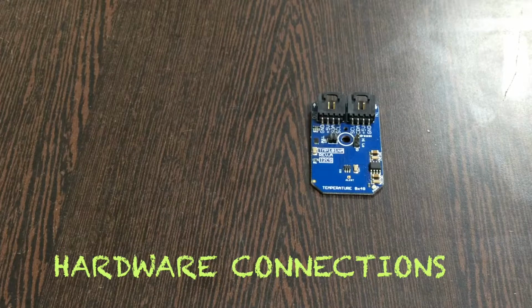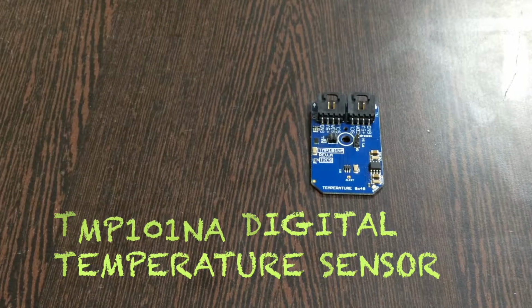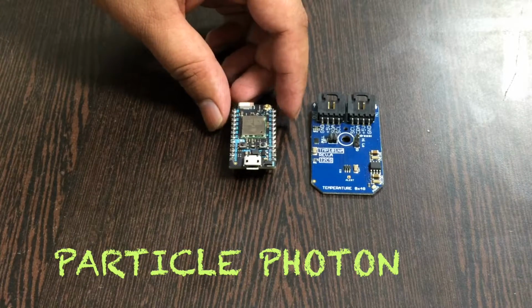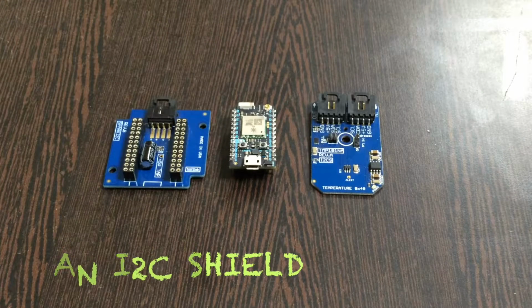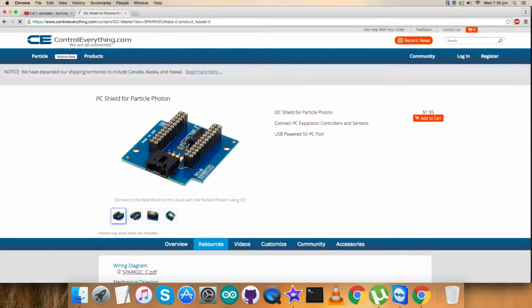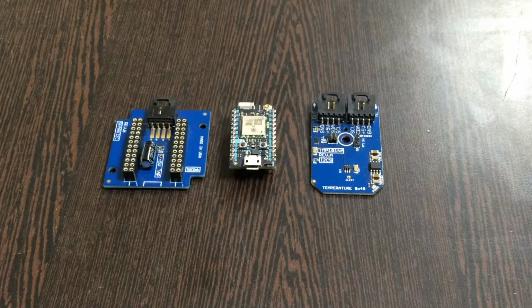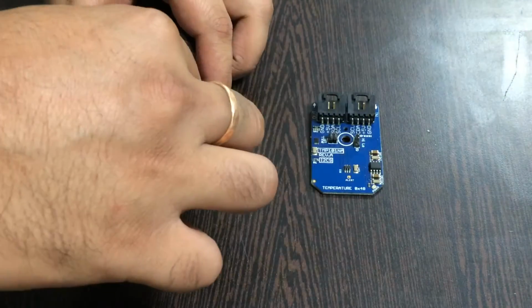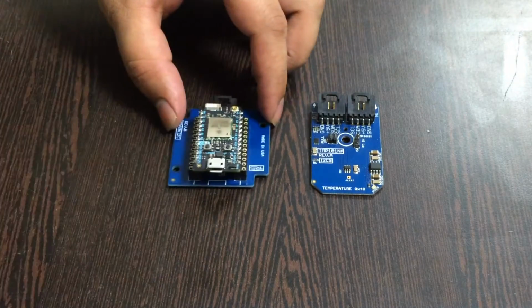First, here is our sensor, the temperature sensor TMP101NA, and this here is a Particle Photon. To make a connection between the Particle Photon and the sensor, we need an I2C shield, which is available on the website controleverything.com. The reason we are using this I2C shield is to make connections with other I2C devices a rather easy job. So gently press the Particle Photon onto this I2C shield and make a connection.